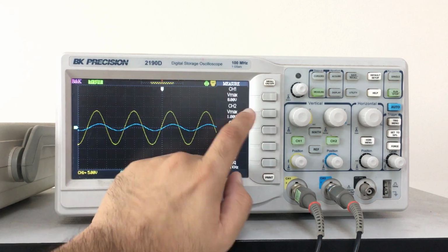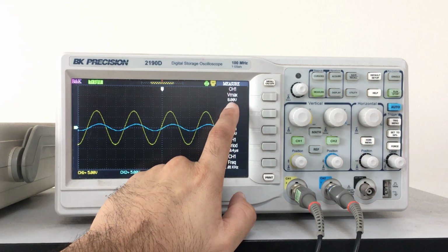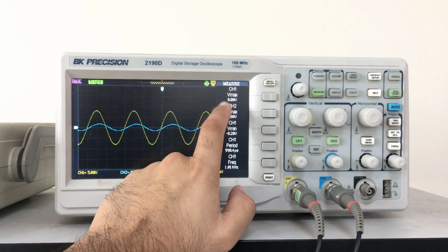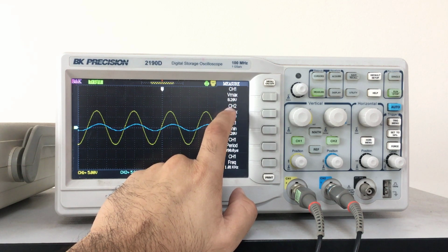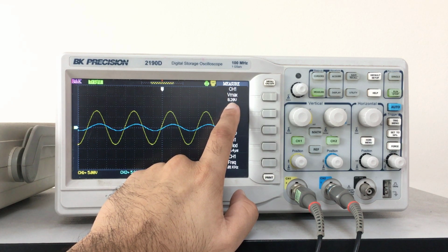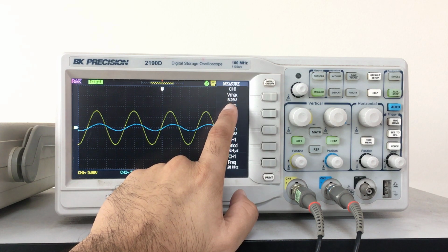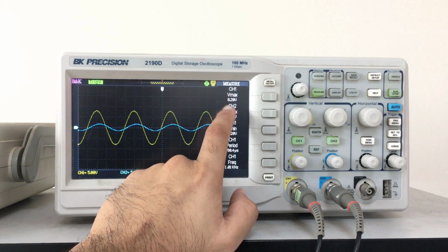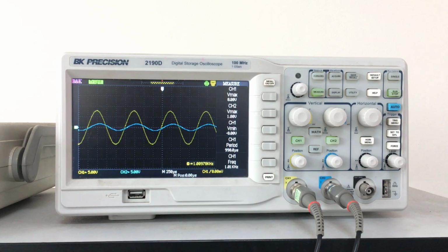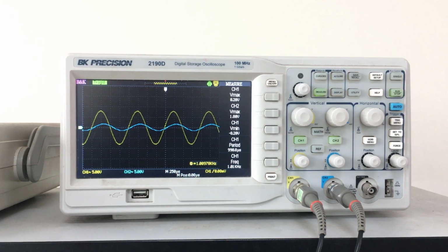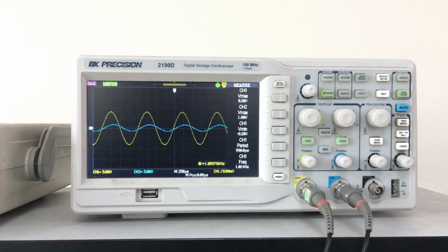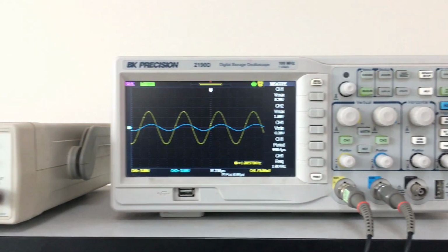So first of all, we'll have to adjust the peak voltage of channel 1. So our required source voltage is 3 volt peak, which is 3 volt max. So we'll have to adjust the amplitude until we find 3 volt max in channel 1. So we will do that by adjusting the amplitude.